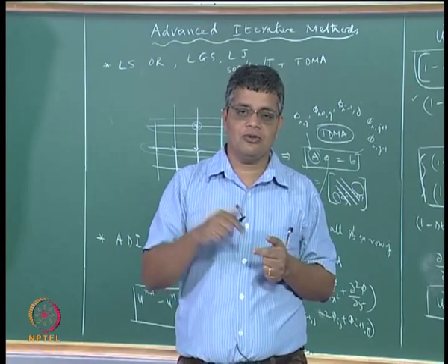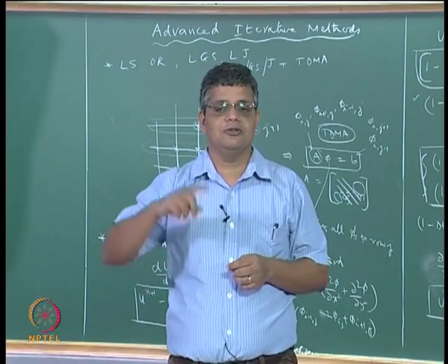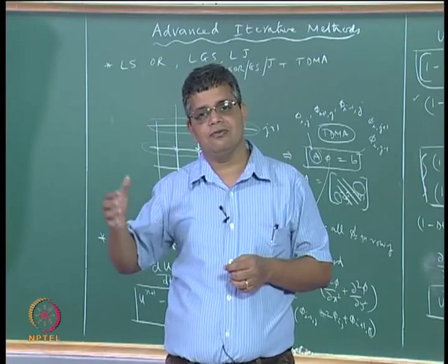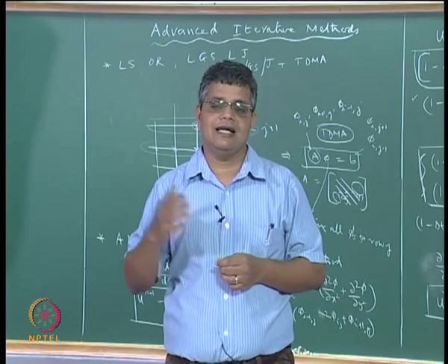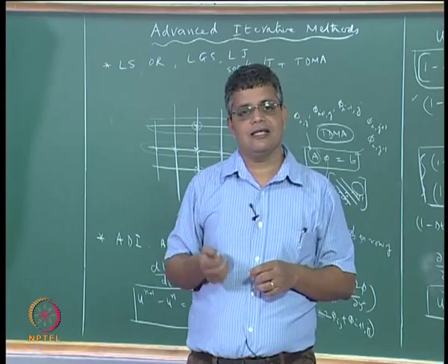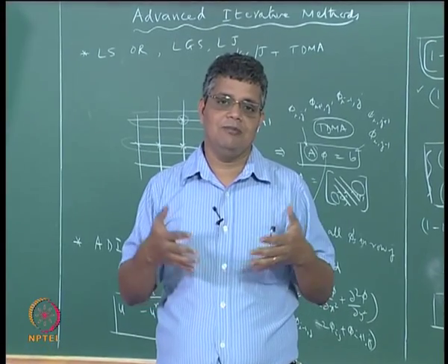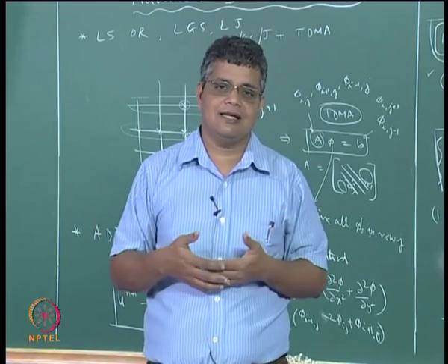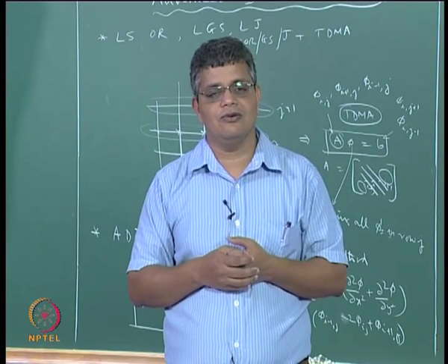So we have to balance the overall cost, and we have seen that in the case of basic iterative methods you go through some initial period in which the residual may not be converging very fast, and finally it goes into the asymptotic convergence rate at which we can realize the n square type of benefit. So if you can alter that rate of convergence by bringing in more implicitness into the solution, because implicitness means that the boundary conditions information is traveling faster, then we can get overall convergence faster.